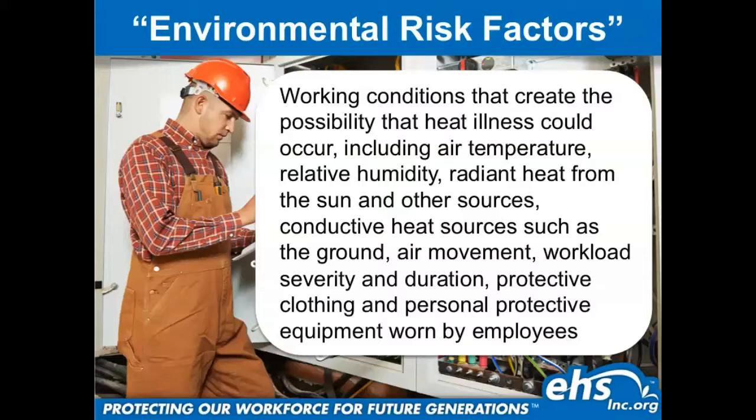Radiant heat: even if you're working in an environment in which it's only 75 degrees, you may be working near a machine that is kicking off a lot more heat than that. To that person in that immediate environment, it may feel significantly warmer. Radiant heat is not going to just radiate through the whole building. Maybe at one corner of the building it is only 75 degrees, but in that one section in which the machines are going and kicking off a tremendous amount of heat, it may feel more like 85 plus. As far as measuring, that needs to be taken into account as well.